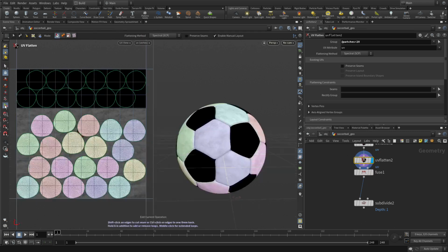Now if we go back to the handle tool, we'll go back into this, which is what we want to work with. So what we want to do is click on the pin vertice option here, and then we're going to shift click on that point right there, and that will allow us to get one of these sections.